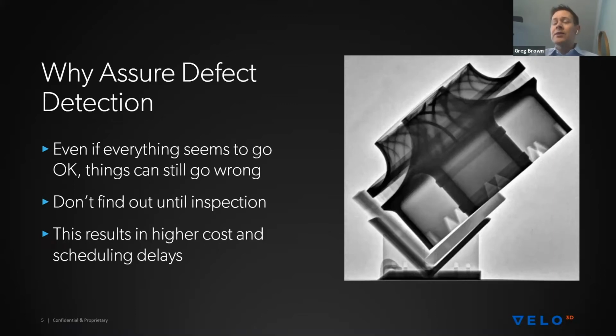you only get that well after the print is done. And so what do you do when you're in a high volume serial manufacturing setting where you're trying to make many parts sequentially? It's not okay to find out that a part has gone bad, or something in the machine has gone bad, a month after it was printed, because then you might have a month of WIP in process. Everything that was printed from that date might have to be scrapped.